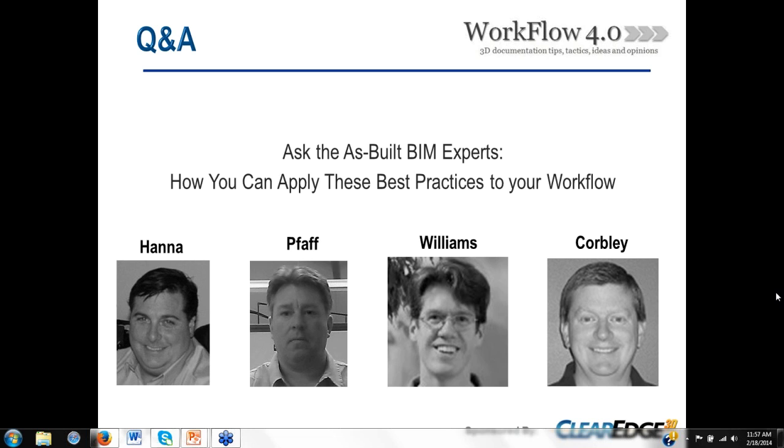Mike Path, how did you deal with surveying in U.S. survey feet when Revit doesn't have that unit? We dealt with it by doing our modeling one-to-one. As long as the model is in a one-to-one environment, moving it over to U.S. feet is not that big of a deal, as long as you go forward with the Revit model as a one-to-one. Does that make sense?